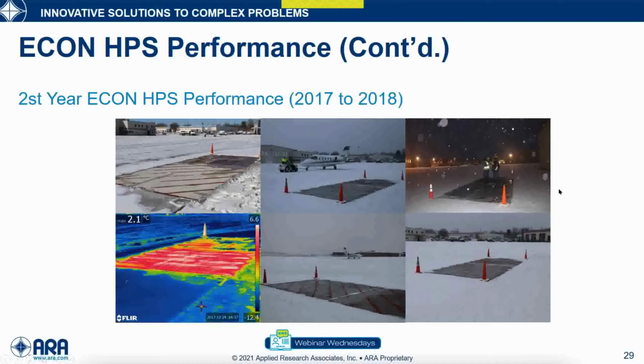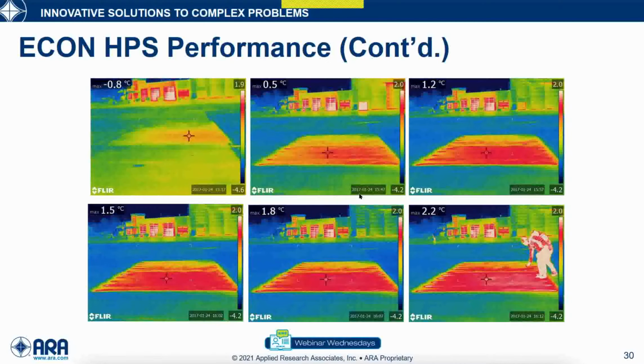And this is why the snow falls. So one thing I noticed is that when the snow falls and touches the surface, it melts right away. So the efficient way is to just turn the system on in advance, like an hour in advance, when you see the weather event if you have snow. And if you wait to turn the system on after the snow has accumulated on the surface, it's going to take a longer time, and we don't recommend that way. Unless this is not an important area, then yeah, you can use this operation.